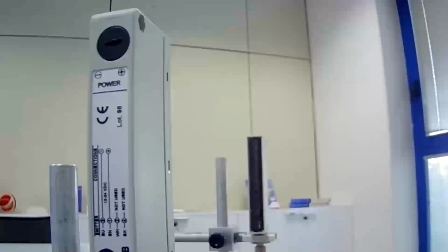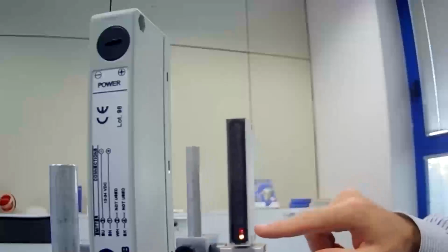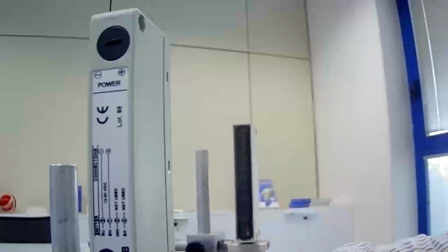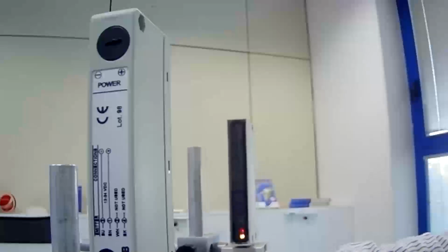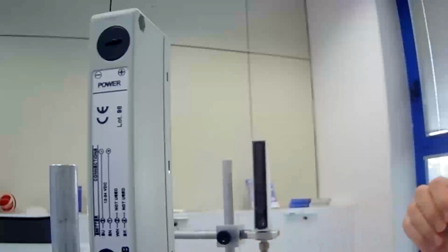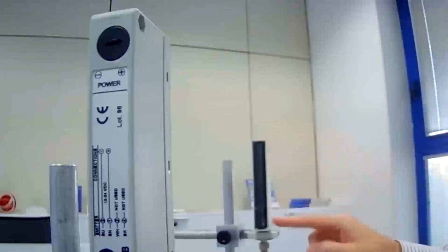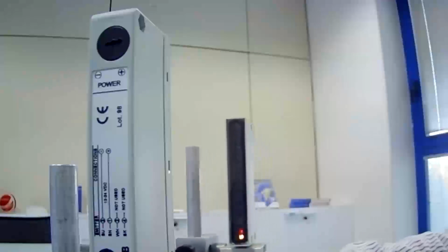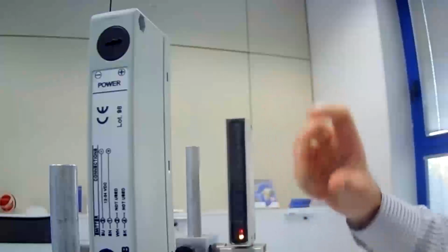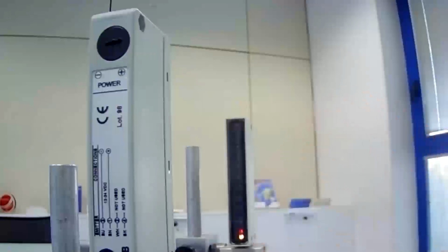And now we see what happens if we go too close to the emitters. As you can see here, the output switches. So if we go too close, the output is activated. The reason is that since this sensor works with total beam crossing technology, each beam emitted by one of the emitters has to be received by all the receivers. If you are too close, some beams are missed, and so the sensor behaves as if there is something in the middle, so the output is continuously switched.